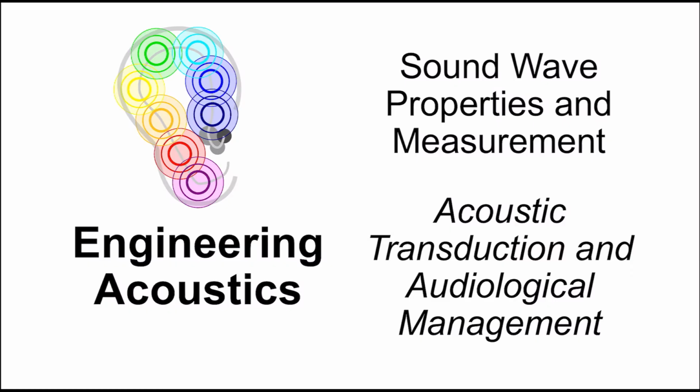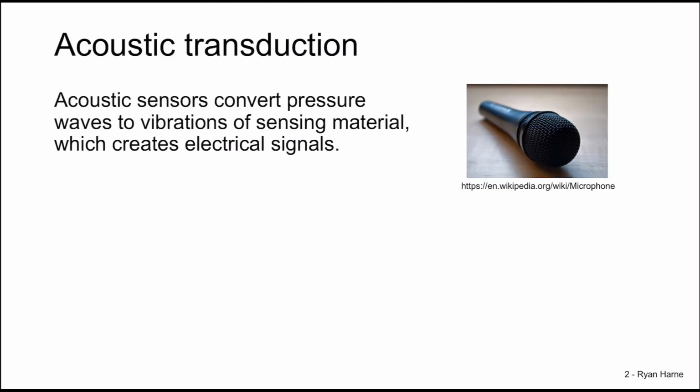In this video, we'll learn about the fundamentals of acoustic transduction, as well as the basics of audiological management. So let's get started. Acoustic transduction is the conversion of acoustic energy into energy in another domain. For instance, microphones. These are acoustic sensors, and they convert pressure waves to the vibrations of the sensing material, such as the polarized diaphragm, and then that in turn creates electrical signals, which in proportion to its sensitivity tells us about the measured acoustic pressure.